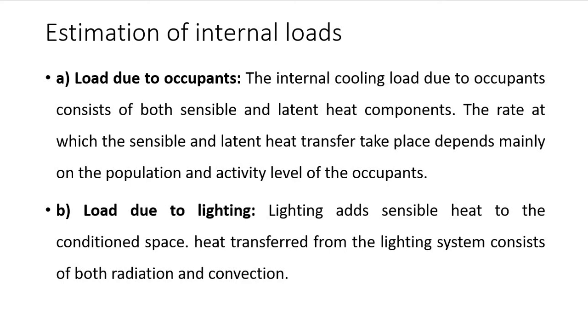So the rate at which the sensible and latent heat transfer takes place depends mainly on the number of occupants and the activity level of the occupants. If all the occupants are sitting idle, with no activity, there will be only a limited amount of energy emission. And if we consider the case of a gym, where all the occupants are actively involved in exercises, they will emit a high amount of energy, and the amount of latent as well as sensible heat load will be more.